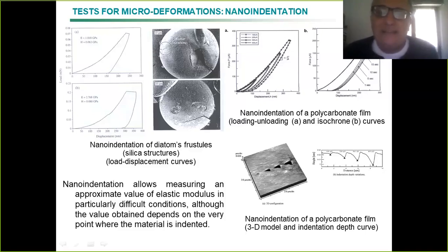You want to widen, to broaden the dimension of the hysteresis cycle, because as you may know in cars, if by disgrace you have an accident, what the car is supposed to do is to absorb damage so that you are not affected. Which means that the hysteresis cycle needs to be as large as possible. So you would better use a polymer, a composite, which absorbs a lot of energy, resulting in large hysteresis cycles.